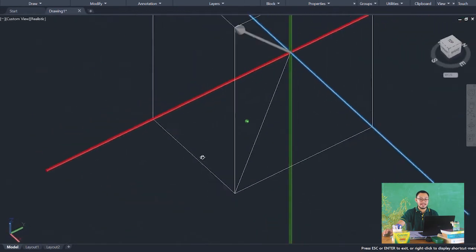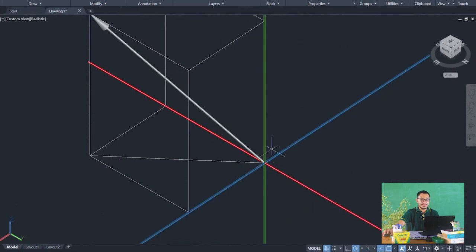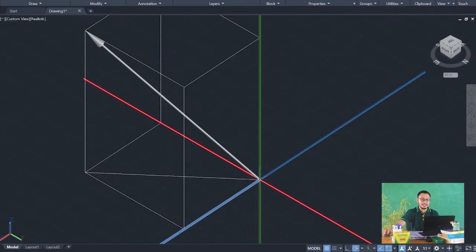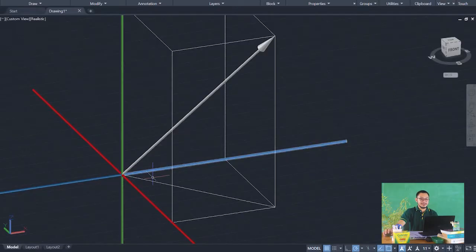The component of your y is from the origin to this point here. Okay, that is our component for y. And for our z, the distance from this point up to this point along the z-axis. So that is your z component. So how are we going to determine the x, the y, and the z components? If your instructor gives the angles here and here, in this case, you can get your fz and your f prime. So, what are fz and f prime?